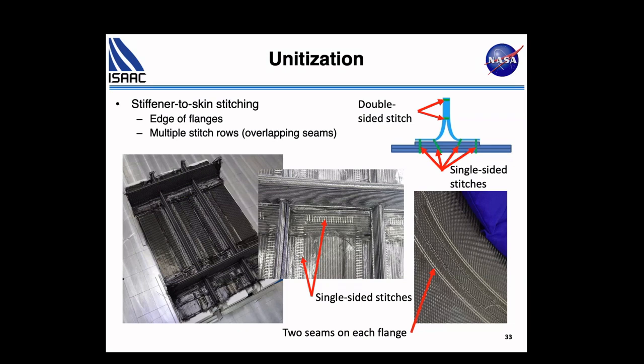The other advantage which we have with stitched structure is, like I mentioned, you want to build a large part without having to come back in and put in all those holes. That's what's called unitization. So instead of having lots of little pieces that you end up putting together, you build one big part, like that panel that you saw on the earlier chart. That can save a lot of time, but it also means that you've got a very large part that you're moving around, and if something does go wrong, you'd better be able to make a repair to it. Those are the kinds of advantages, and things you have to think about when you're actually building parts.